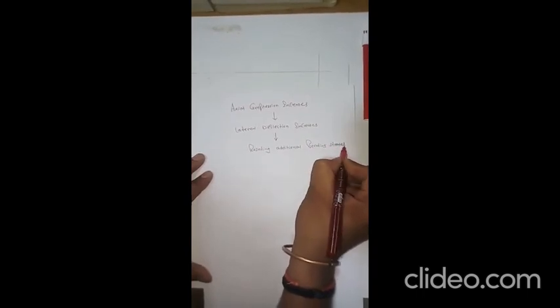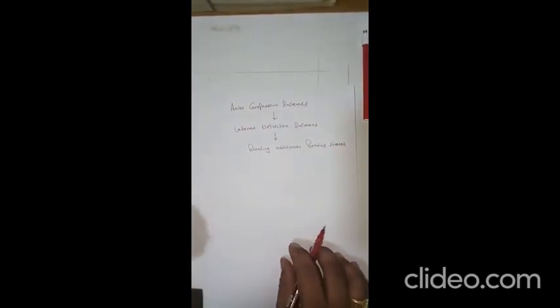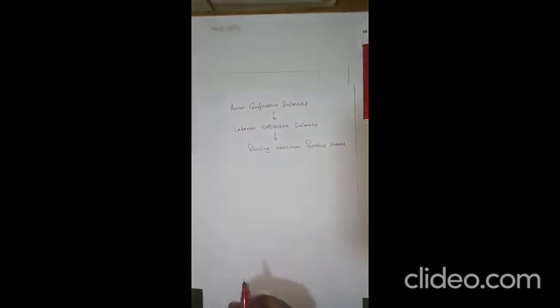If an engineer makes columns transfer load axially from top to bottom of the whole building, he will be a perfect engineer. But practically it is impossible. It is not just a small possibility, it is impossible. Why? Because the load in the structure won't always be vertical, right? Your load won't always be axial. There will be lateral forces, there will be eccentric forces, there will be lateral forces in terms of wind, in terms of earthquakes. So all these forces combined together should transfer into the column axially. Do you think that is possible? No. That is impossible.